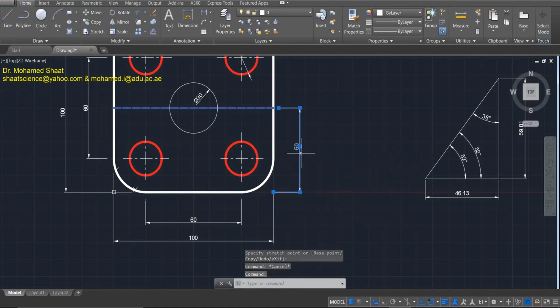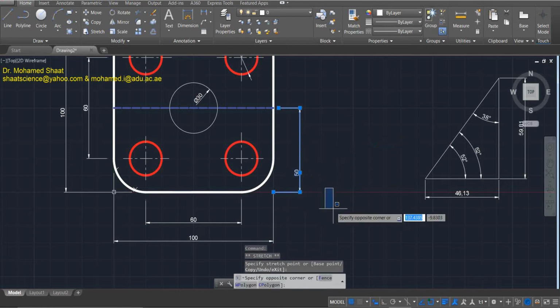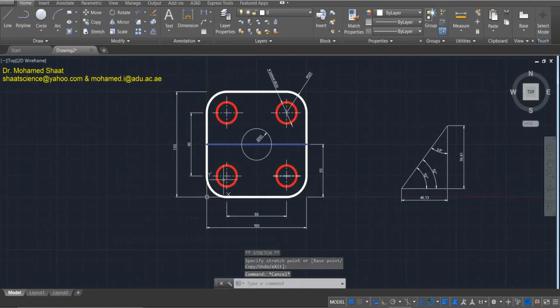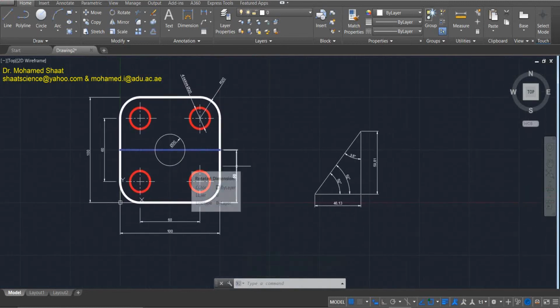And try to have the text in the middle. I can move the text, I can squeeze the text to shift it up or down. This is not preferred. It is preferred to have it in the middle of the dimension line. Make sense? So all of these are standard things in terms of dimensioning, and I've discussed with you how we can add the dimensions.